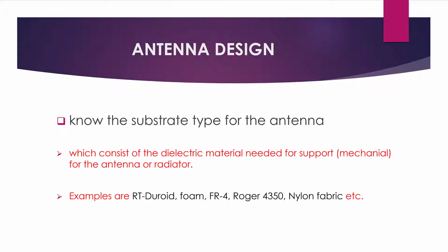Now to achieve maximum efficiency, normally we use the Rogers 4350. That is the best substrate to use when you want to achieve maximum efficiency, but the size of this substrate is much bigger and it is not cost effective. That is, it is very expensive to purchase.